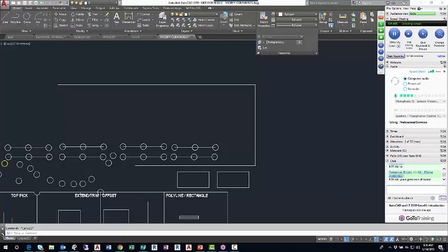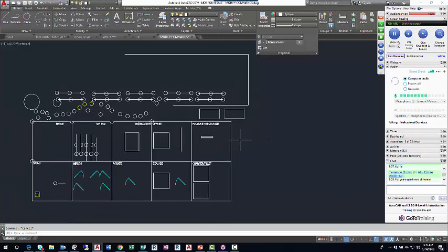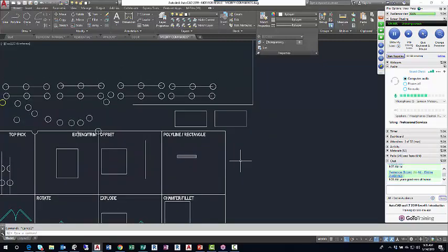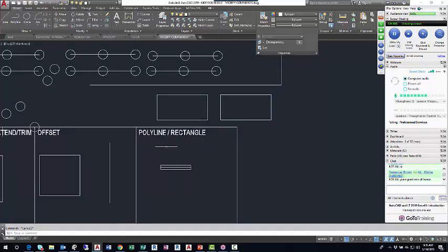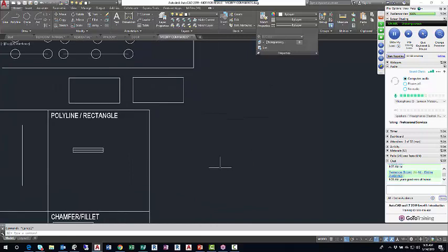But really, the differences between line and polyline are not truly revealed until after you've placed it, or why it is called an advanced draw command, is that you have some command line options. If I click polyline, there are no command line options until after I left click and start. Now that I've left clicked, I can switch into an arc. I can create an arc with my polyline.